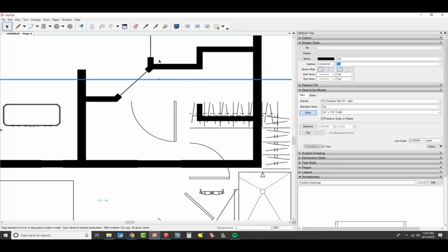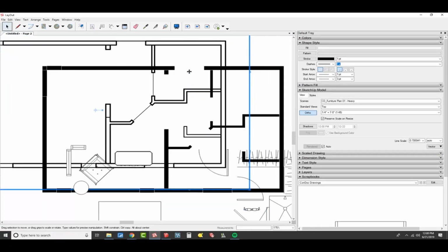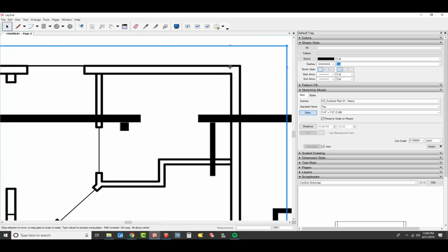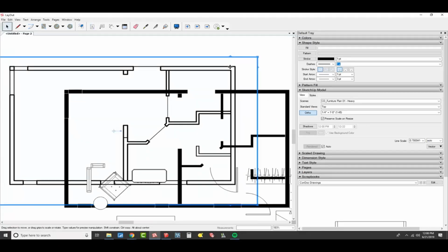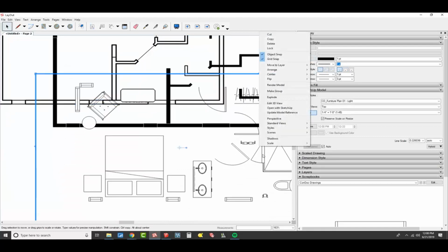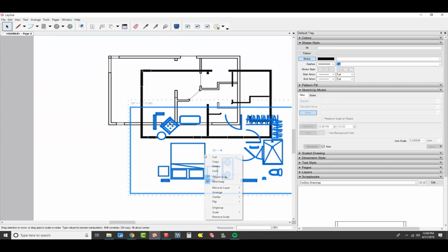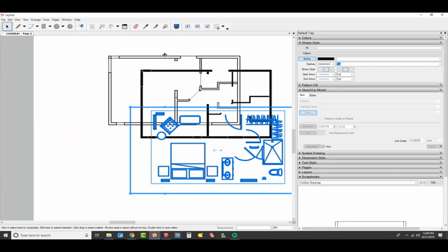Then we have a heavy viewport. Now I can scoot that one over here, and you can see that heavy is at 0.7. So our line weights for this one drawing go 0.22, 0.44, 0.7, and then it's going to go 1.4, and then you can see the real heavy stuff is going to be like a 3. So let me explode this, and I'm going to explode this, and we're going to just take a look, and I'll just ungroup all this and ungroup all this.